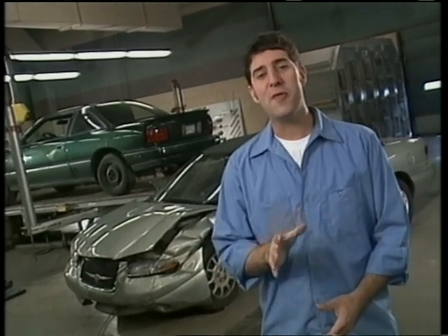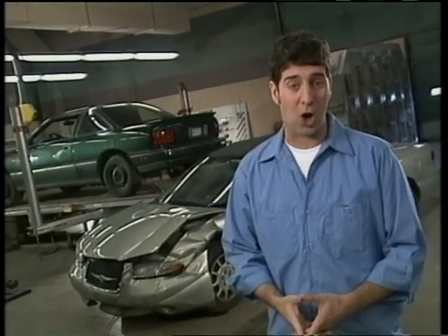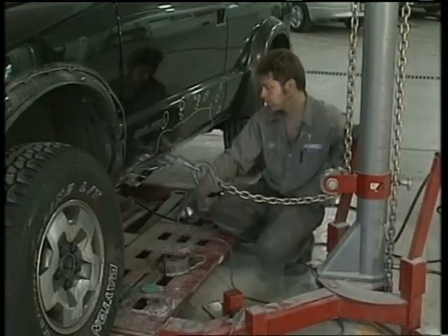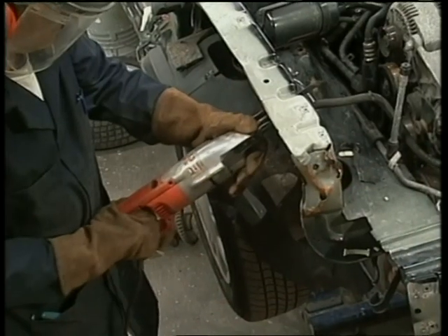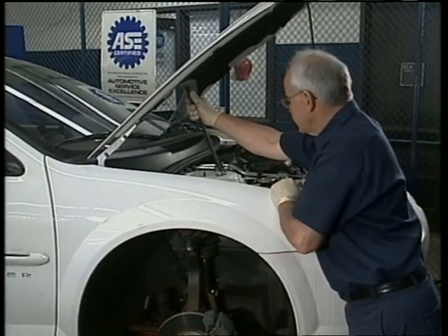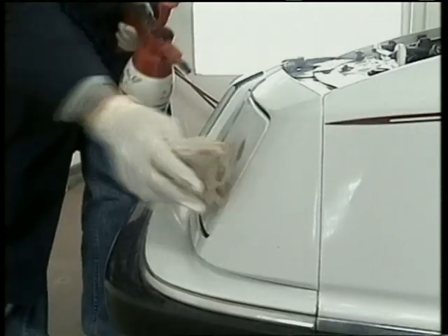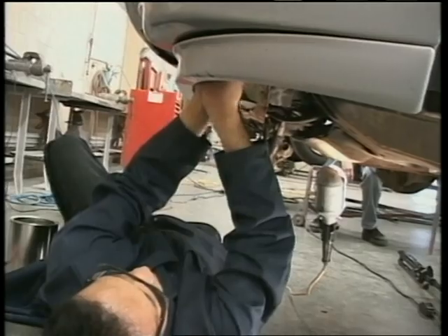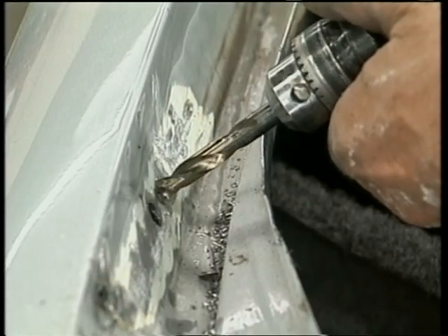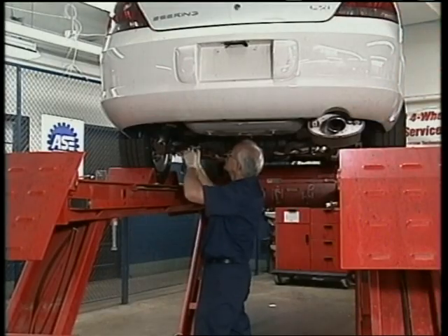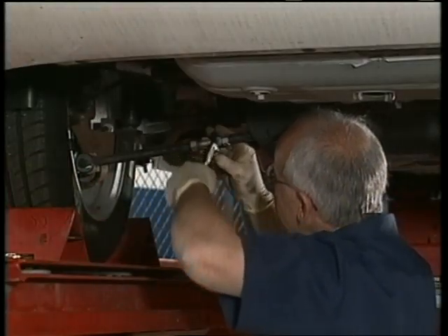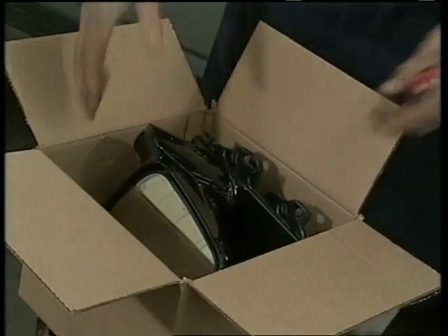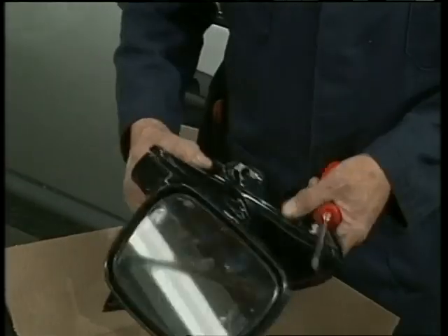Other factors to consider when writing an estimate are the time needed to set up the vehicle on a frame machine and diagnose the damage, the time needed to straighten the frame and to cut out damaged parts, the time needed to align parts, time needed to remove tar, grease, and undercoatings, time needed to free up rusted and frozen parts, time needed for drilling and plugging holes, time needed to check suspension and steering alignment, time needed to rebuild or recondition used or aftermarket parts, and the time needed to replace any damaged accessories.